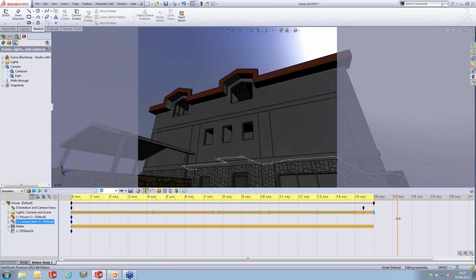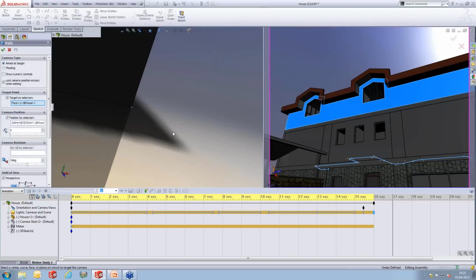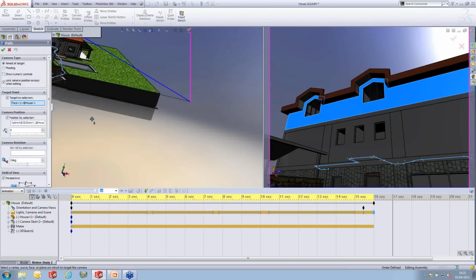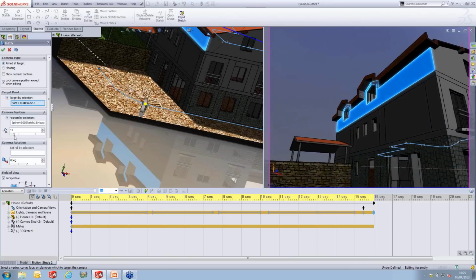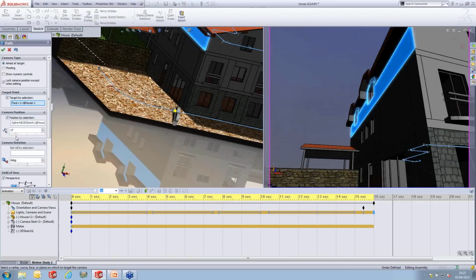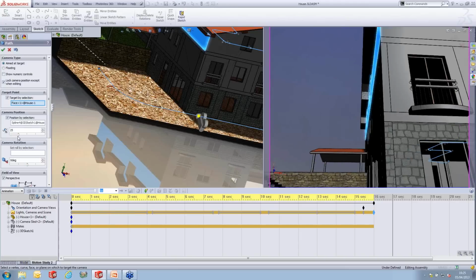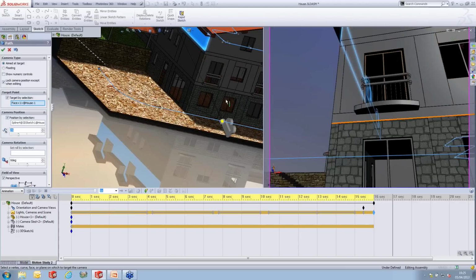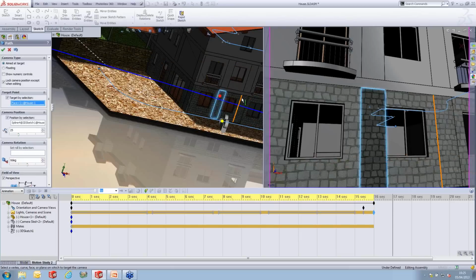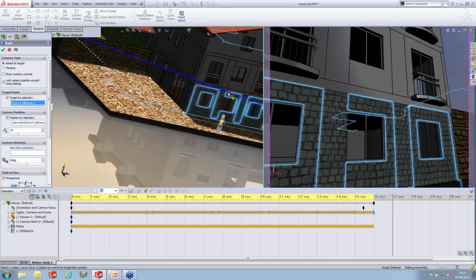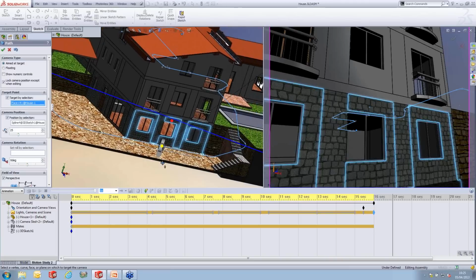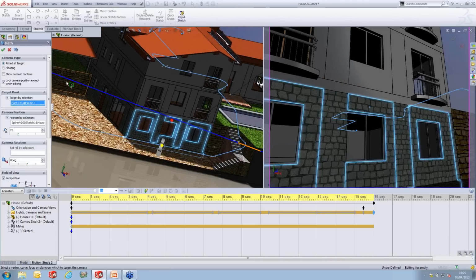Now moving round to about 17 seconds, I can just shift around the side of the house to have a look at it in a bit more detail. This time I will be editing the path camera, and all we do to actually get it in position is just physically drag this slider the percentage along the item we want to have a look at. And this time, instead of just keeping my point of focus right in the middle there, I'm actually going to be moving it around the house as we shift along. So I'll shift it to this side panel here possibly, or maybe about there, a bit more of a centralized view. Okay, you can see you can switch into any of the views by clicking in the graphics area, and it just switches what the camera is looking at.